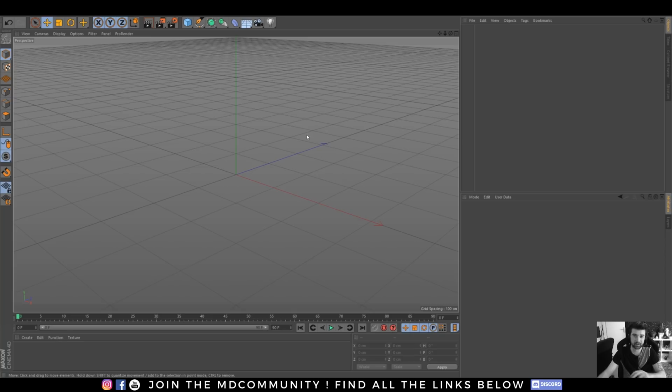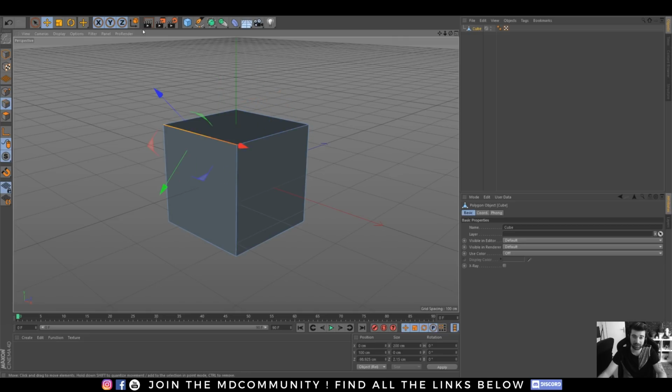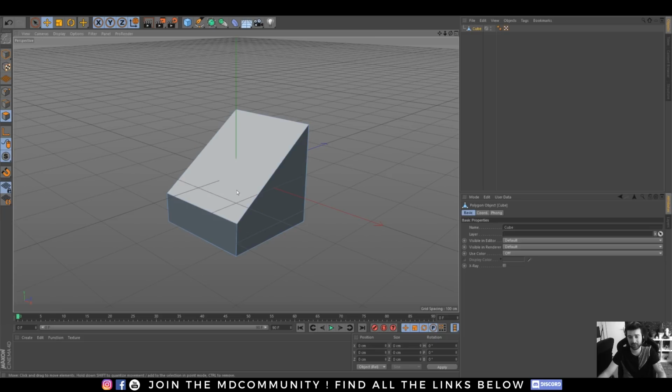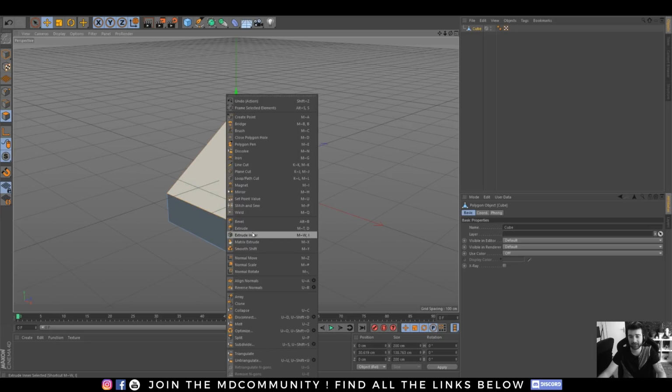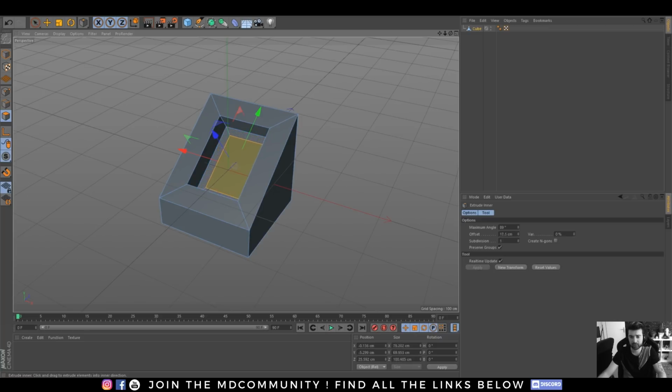The first technique is the sub-D modeling. This is really classic. You have one basic object and you will use different operations based on points, like moving the points, edges, like moving the edges or applying bevels or sliding edges, and many others, or based on faces. For example, here I can inner extrude my mesh and I can extrude like this. I can do another inner extrude and I can do, for example, this.